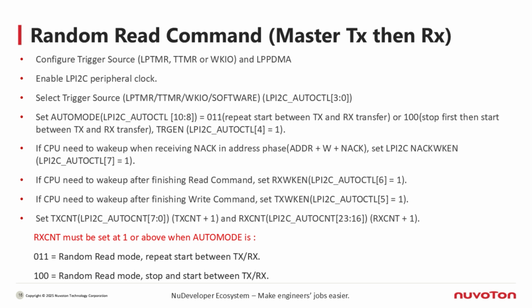For the wake-up mechanism, if you want the CPU to stay asleep until the task is complete, set RxWKEN to 1, so the CPU wakes only after all data is read. It's also recommended to enable NACKWKEN to immediately wake the CPU if there's no response from the slave.